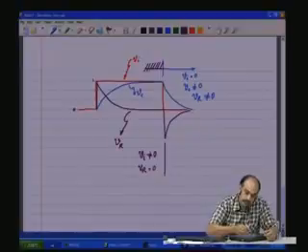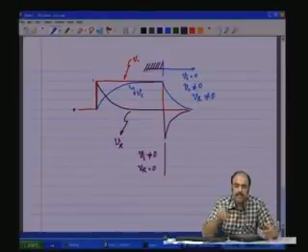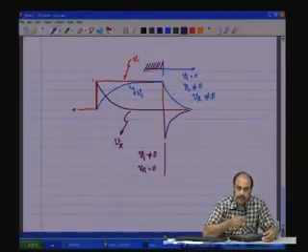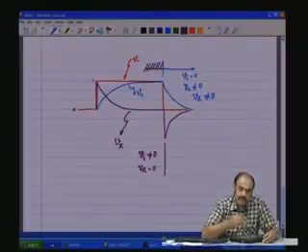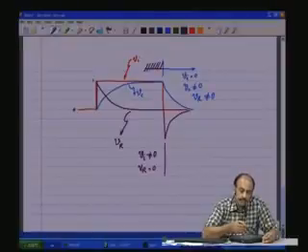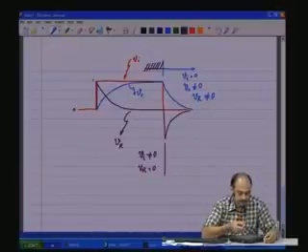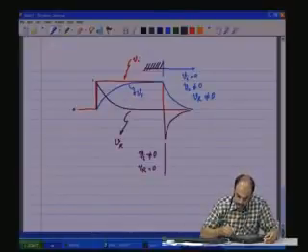Vi is made 0, but the vehicle speed is coasting, gradually decaying to 0, which means the output is there even though the input is 0. That is the existence of the pole, and the decay depends upon the position of the pole in the S plane. Likewise, for the zeros, if any particular variable decays to 0 like a differentiator, then there is the existence of a 0. So, this concept you should get clear.